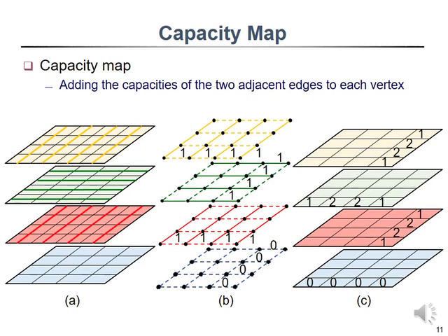In Figure A, we assume that there is only one track path through every G cell, except for metal 1. In metal 1, there are a lot of access pinpoints, so we choose not to assign any segments. Figure B shows that the edge capacity is 1, which represents only one segment can pass an edge.